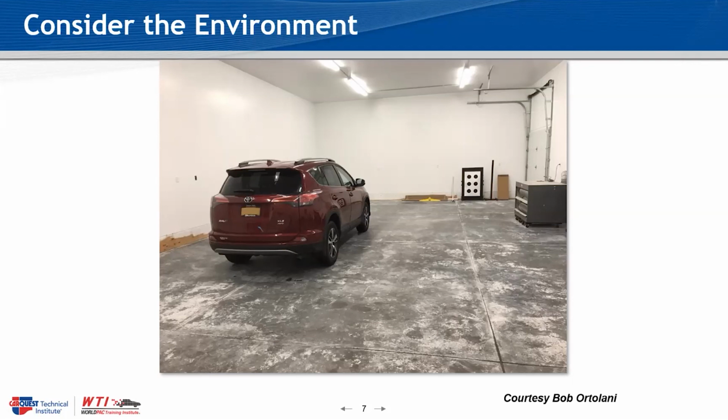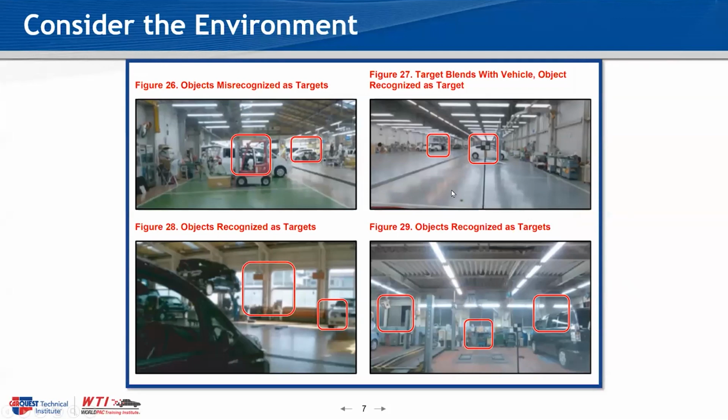A static calibration is one that would involve a target like this one seen here in the picture. A dynamic calibration is one that would involve putting the vehicle under certain driving conditions while performing a command function to a module or series of modules in the scan tool. And again, it's so difficult to pack all the aforementioned needed information about advanced driver assist and cover this case study. But this case study we're going to use is going to kind of highlight some of the possibilities that are out there. Another good example of area is some pictures taken from Toyota service information.